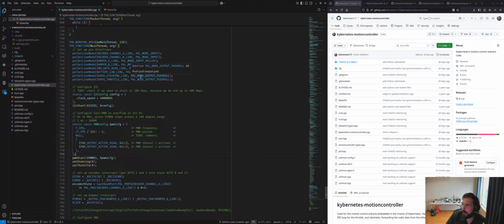Tickless mode, by default, uses a higher precision timer on the ATmega328P, which is what's in the Arduino. There's only one 16-bit timer, and that's timer 1. Timer 0 and timer 2 are only 8-bit timers, so they can only count to 255 before they reset.